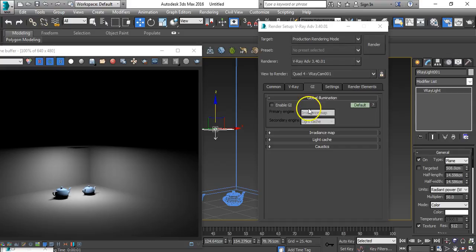This is the big advantage of V-Ray, you know, or global illumination is the main thing, whether you are using Mental Ray, V-Ray, or any other renders. With global illumination, you can make photorealistic. If you don't use this, then you have to create some fake lights here to generate secondary lighting. Okay, but here it's so easy to create the secondary lightings.